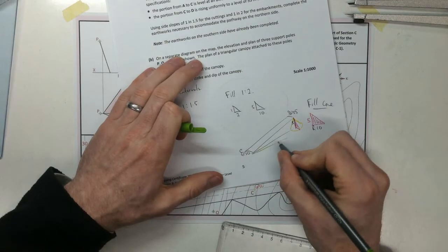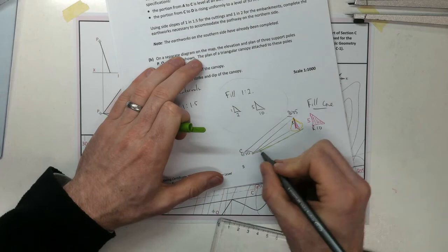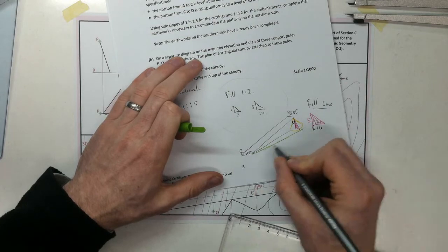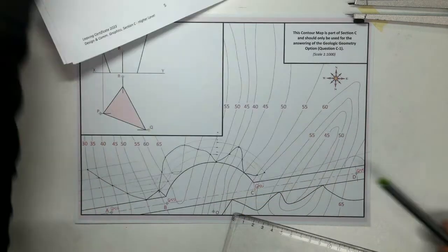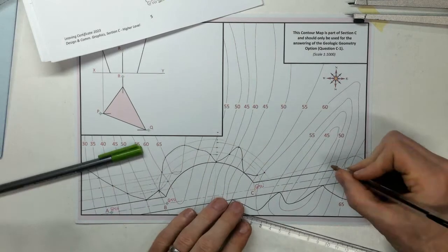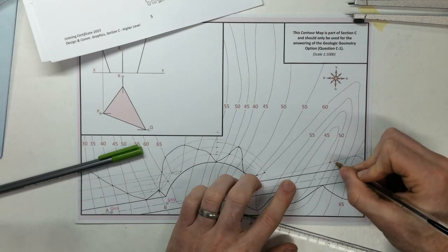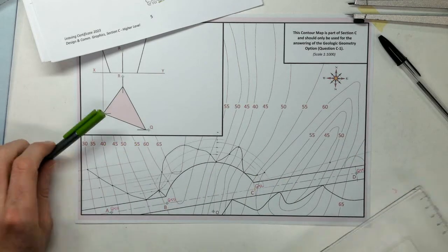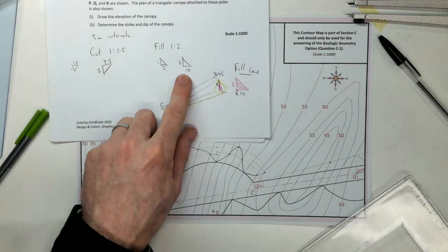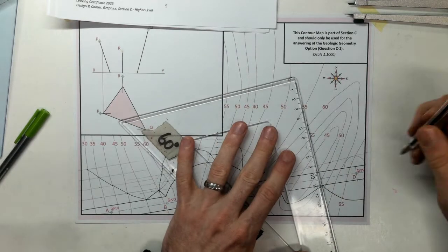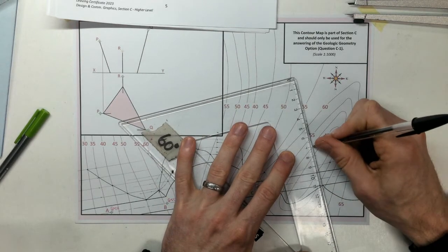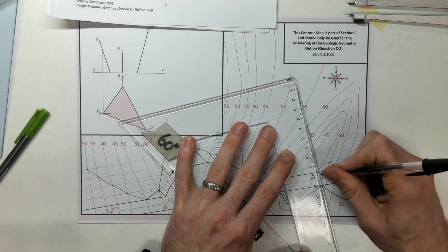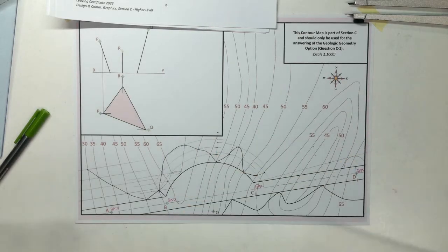Okay, so that line, using another color here, represents this line from the base of my cone to C. So that is at height of 50. Let's go to my 50 here, and we're going to be going up in 10-meter intervals. So 10, 10, 10, and I'll even put one below it just in case I need it.